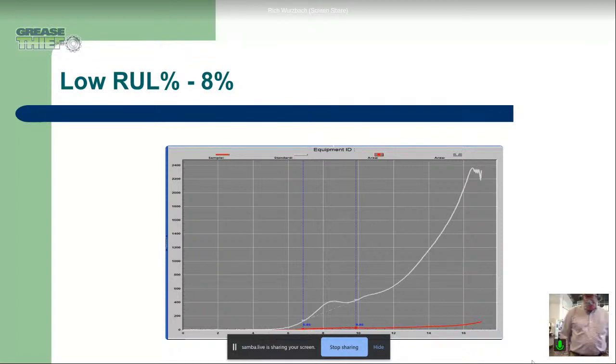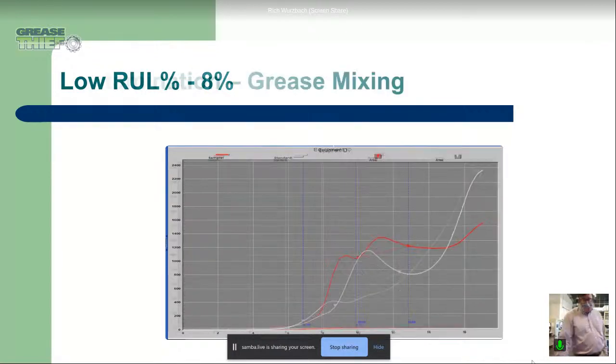So whatever the circumstances were, if this is the normal operating conditions for this grease, whatever this frequency was, it just wasn't quick enough. It wasn't soon enough to rescue that grease, to replenish it, and to continue to protect that particular machine. So here's an example where we want to go back and review and say, we may have to shorten up that interval.